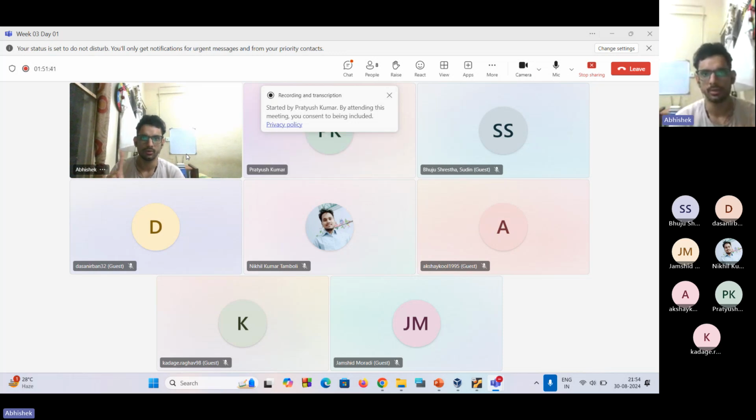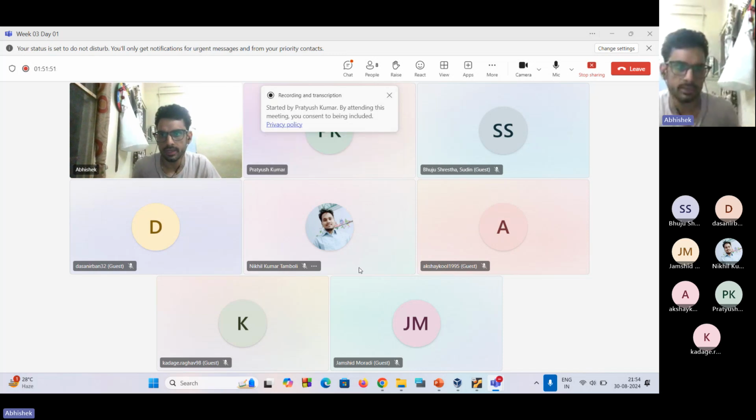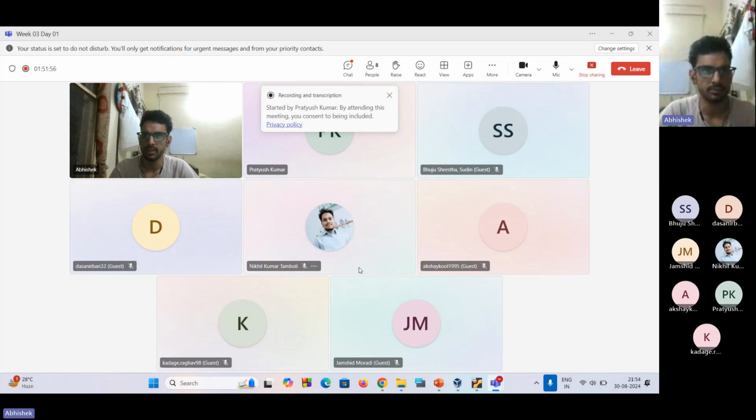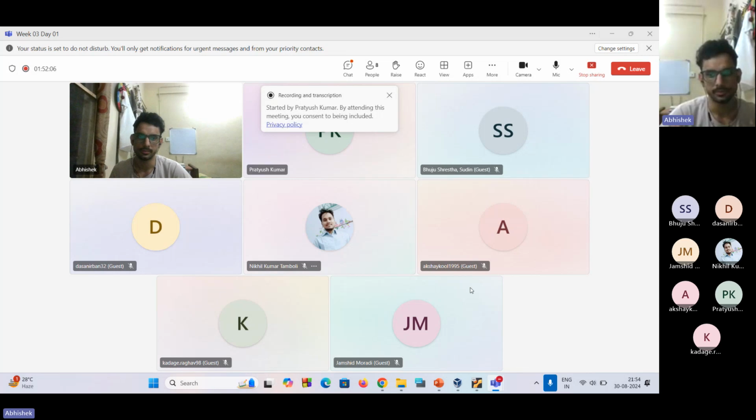You just have to run one command. The hard part is to successfully define the mesh in ANSYS Design Modeler or Gmsh. Wherever you're making the mesh, you have to define everything properly. Otherwise it will not convert successfully in OpenFOAM. So converting in OpenFOAM is simple, but making that mesh in other software carefully is important.